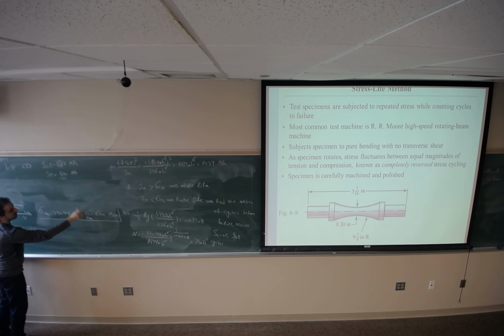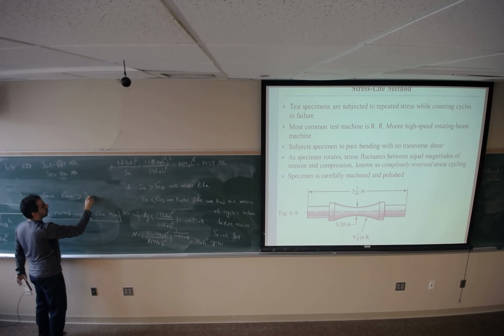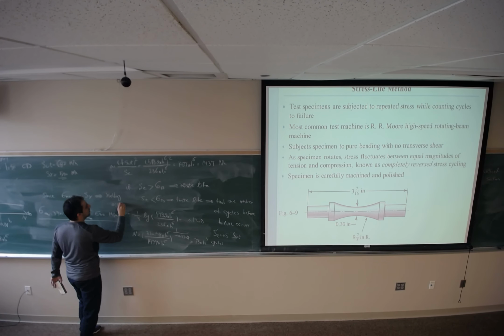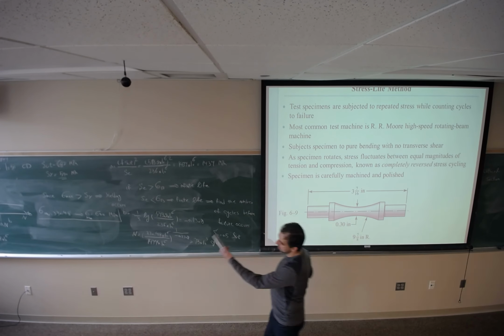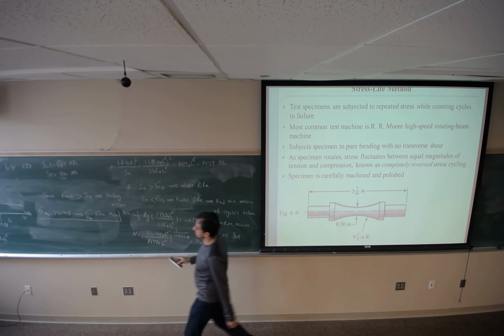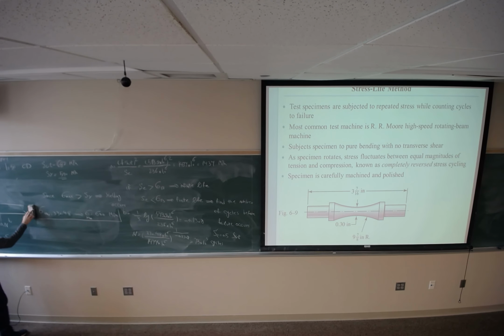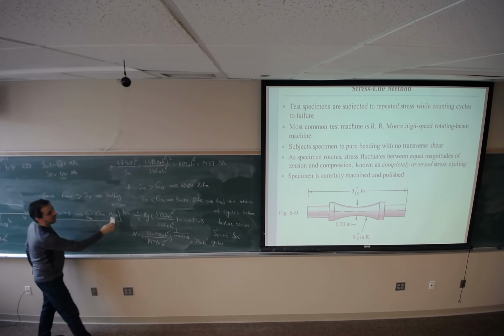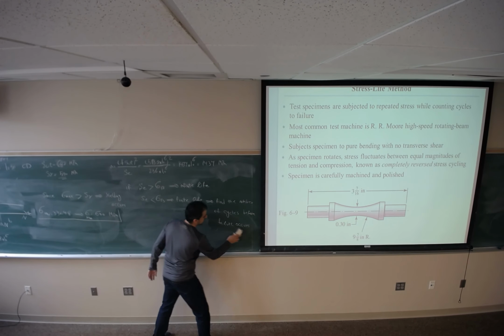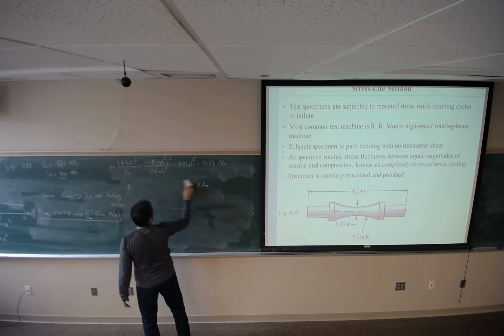Since yielding occurs, there is no need to do failure analysis for fatigue, because it's already failing due to the yield. So make sure that you check this one also, because you may end up with stress greater than yield strength, and you do the fatigue analysis and it looks good, but it's not, because you might see failure due to yielding.